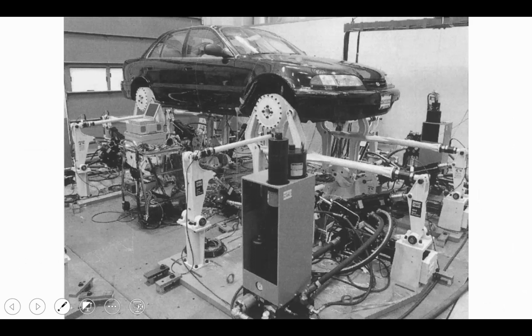And this here is an example. This is an example from our book of an SAE, Society of Automotive Engineering, a type of load frame for applying fatigue loading into the components of a vehicle. We can see that each wheel is independently connected to a system here. We've got an entire suspension control with servo hydraulics that allow us to simulate road conditions. You can simulate potholes. You can simulate rough surfaces and how that affects the vehicle structure.